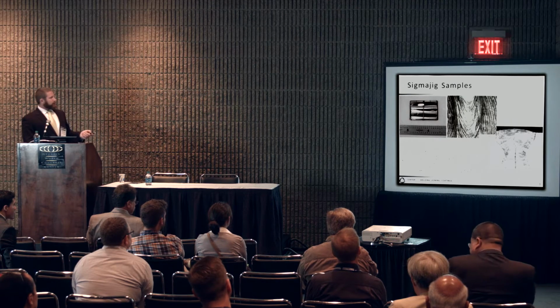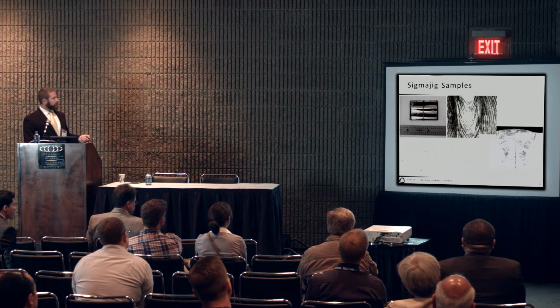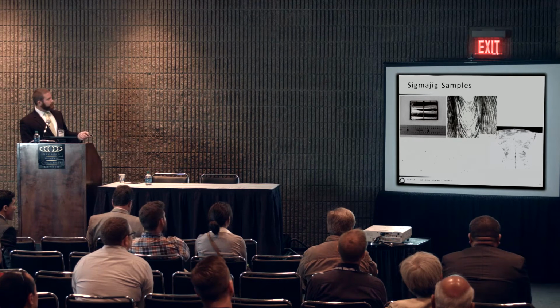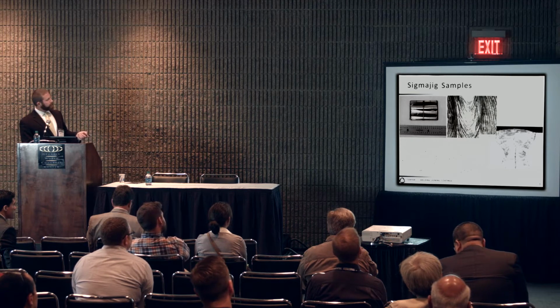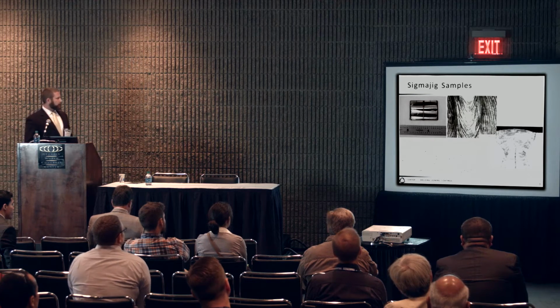So an as-tested sigma jig sample looks like this. This scale is actually in inches, and then the other units are in millimeters here. And so if you look at surface cracking, you typically see the centerline solidification cracks if you do observe surface cracking. But some alloys would show only subsurface cracking. So again, large centerline and sometimes non-centerline cracks subsurface.